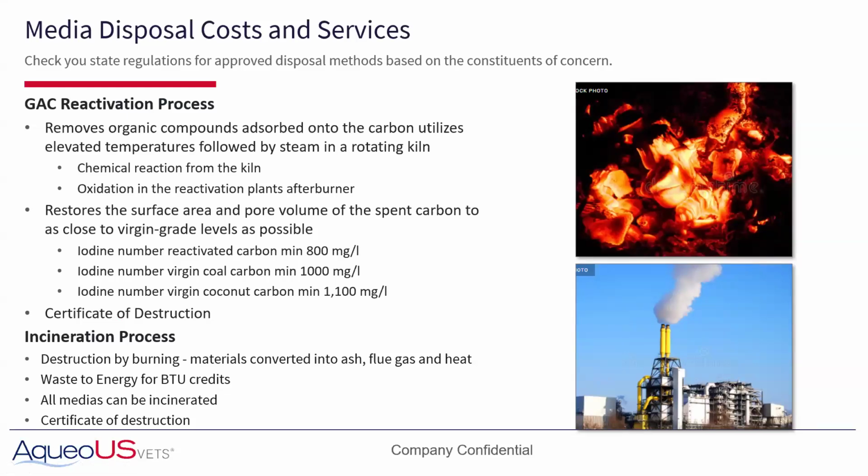There's a little bit of discussion on the reactivation process and incineration destruction technologies. So in theory, you can reactivate the activated carbon. And reactivation is basically sending it back through the same process that was used to make it. This is typically done in a rotary kiln for the drinking water carbons. Temperatures up to around 1,000 degrees C the material is exposed to. So again, if you look at the physical properties of the PFAS compounds, in theory, they should break down. The gas coming off of the reactivation facility is run into an afterburner. So again, this is all so you're not discharging anything to the air. What we're trying to do is restore the material back to the virgin grade.